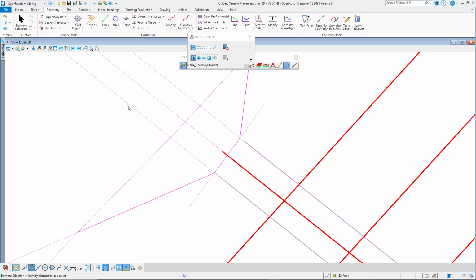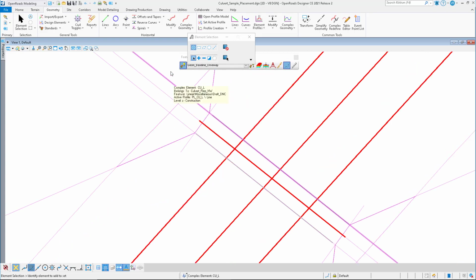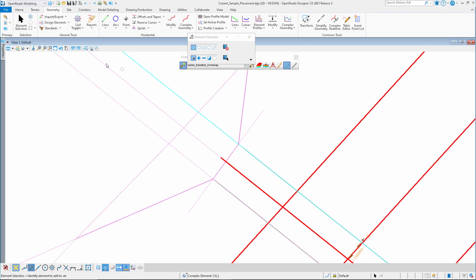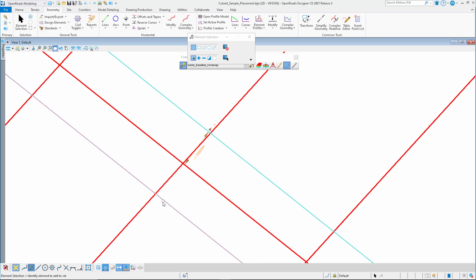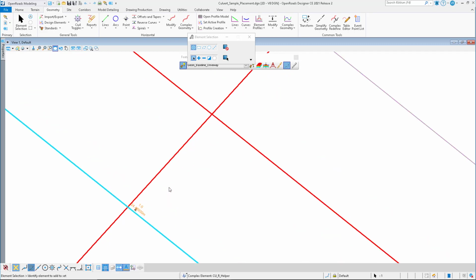We have these two objects that are offsets from the initial culvert line, and if you select them, you shall see manipulators. And at the middle, you see that the default value is minus 1.7, and you have exactly the same at the other side.